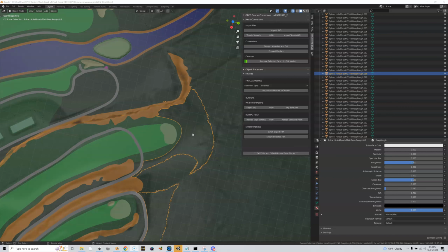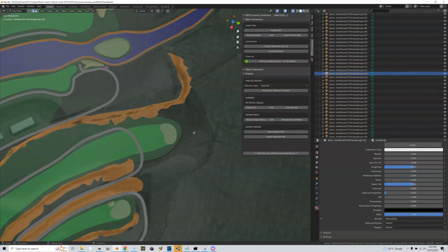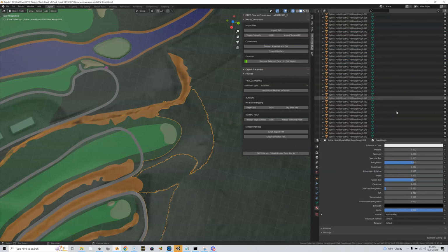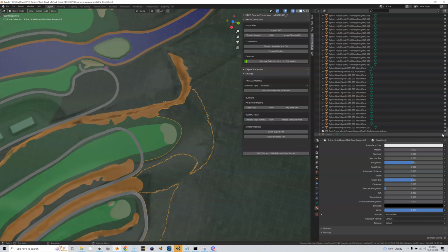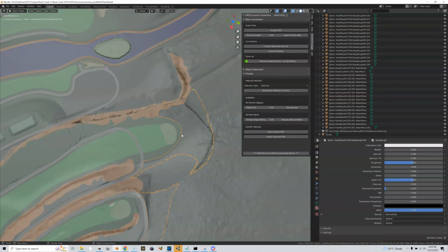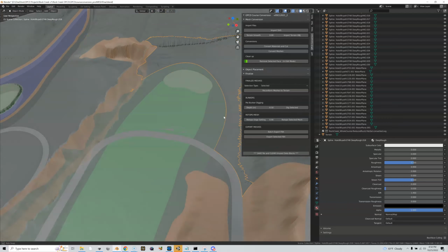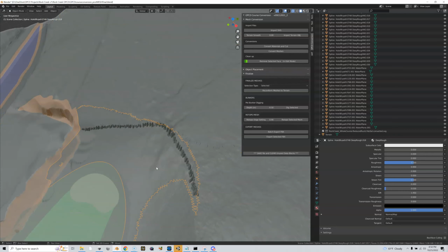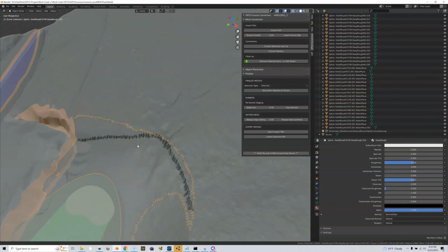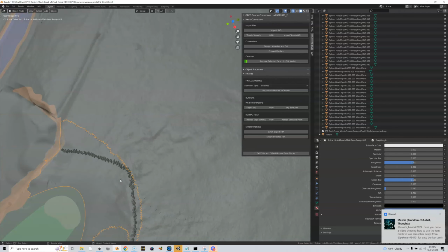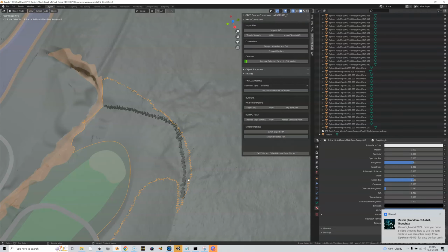So now what I'm going to do is tab into here. Oops, before I do that, we tab back out. I said I imported my terrain. Let me turn it on and you're going to see what happened. Okay, so now you can see where I had marked it is now showing up here. So I can have a good idea of where I want to do this cutting. So if I just go over top here, I'm going to cut this mesh right along here. So let me leave that on, go back here, highlight my mesh, tab into it.